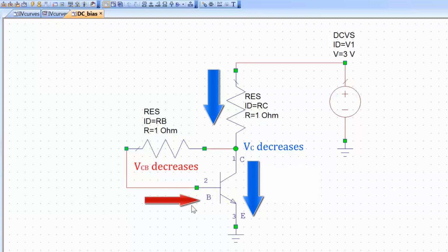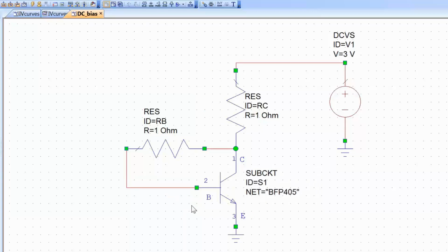So you're lowering the base current, which is biasing your transistor, and because you're lowering that, then your collector current also gets lower. So effectively your collector current can try to increase, but then when it tries to do that, because of the bias arrangement, you end up decreasing the base current, and that has the opposite effect, that of decreasing the collector current. So this provides some sort of feedback loop which allows you some certain stability over temperature, for instance, but also in other respects.